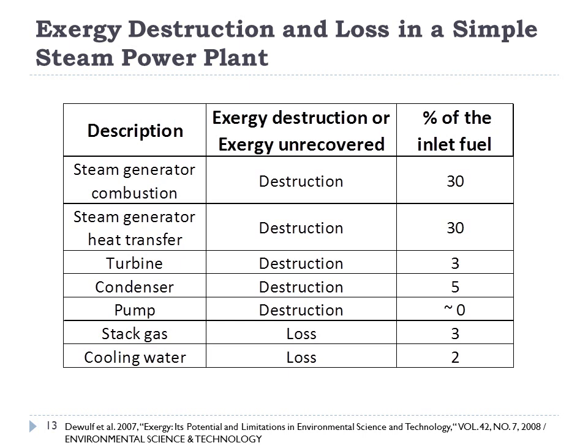And then the last thing I want to talk about is the cooling water flowing on the other side of the steam condenser. That cooling water has a lot of thermal energy, but as you can imagine, because cooling water is only going to be maybe 10 to 20 degrees above room temperature, there isn't much exergy, even though it can be carrying away sometimes up to half of the original enthalpy that was in the coal. It's only carrying away perhaps 2% of the exergy that was originally in the coal.